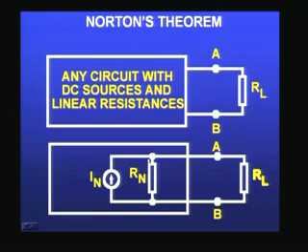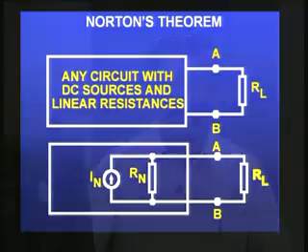They help us to reduce very complicated networks into a very simple scheme, and then obtain the voltages and currents, the equivalent circuits of any arm. If you want to find out what is the voltage or what is the resistance, you can use Thevenin's theorem or Norton's theorem and simplify it, and then try to obtain the actual values of voltage and current.